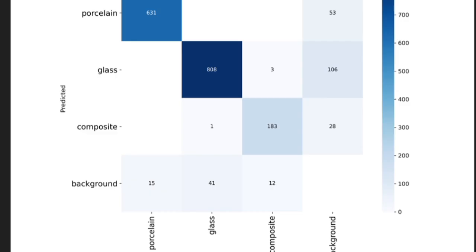From this, we can see it has higher interclass discrimination and very high reliability. For an inspection project, high recall is vital, that is low false negatives between classes. It means when the model sees an insulator, it is very likely to identify the material type correctly, which is essential for power line inspections.